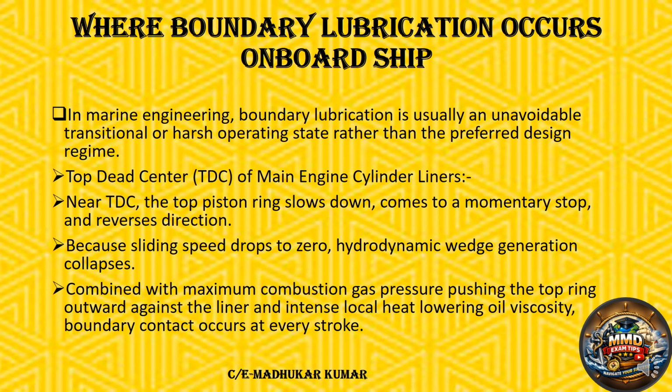Where does boundary lubrication occur on board ship? Boundary lubrication is usually an unavoidable transitional stage. You can see it at the top dead center, TDC, of the main engine cylinder liners. Near TDC, the top piston ring slows down, comes to a momentary stop in a transitional period, and reverses direction.